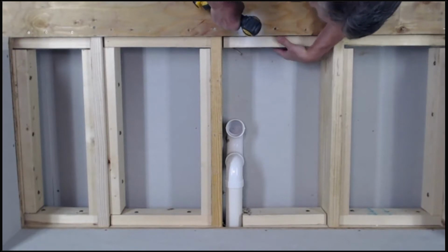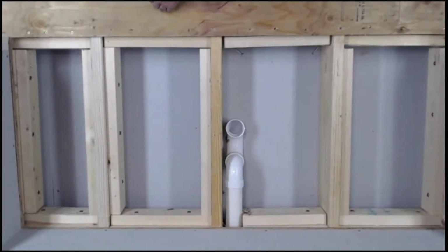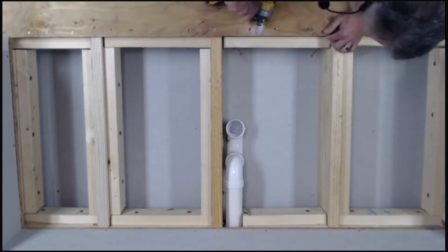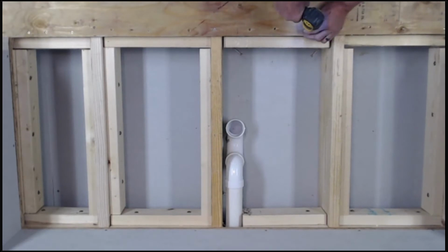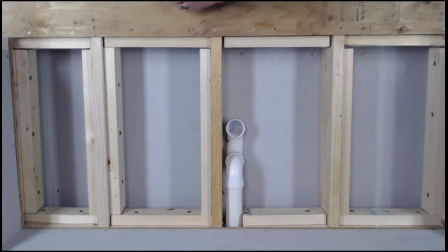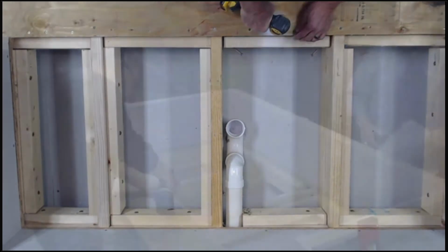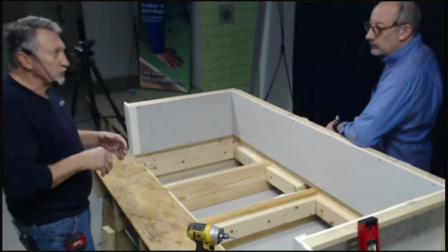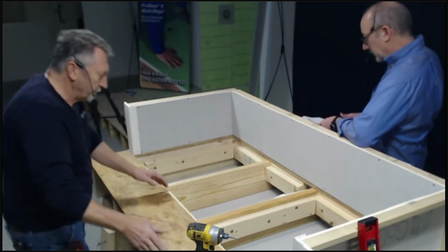We have a question. Yes. The question is, there are other products on the market that will accommodate a reduced or lowered subfloor. Is that okay to use in this particular situation? Dave exactly mentioned that there are some pre-manufactured products that are available. They're a good option. They're another option. Obviously, the 2x4 situation here is readily available everywhere. But yeah, there are other products. And I understand those products will get you down to about 11/16 because there's a little bit of buildup with the metal on the top of that. Yep. Very close.